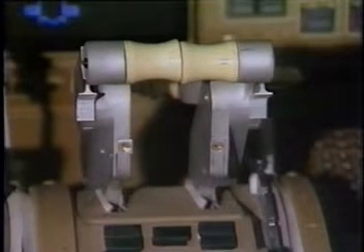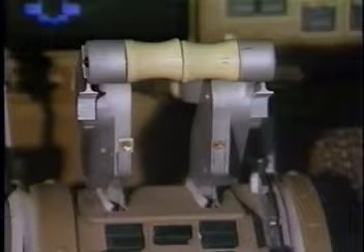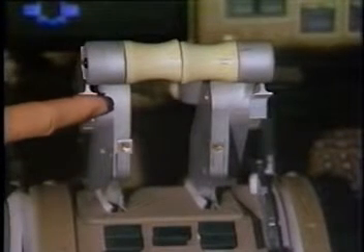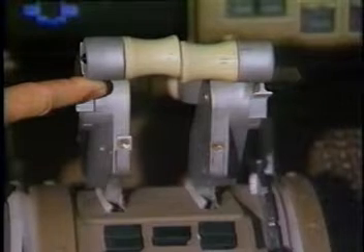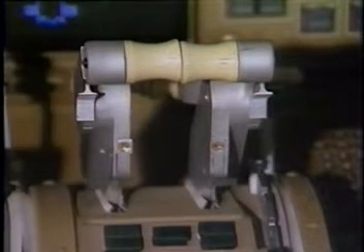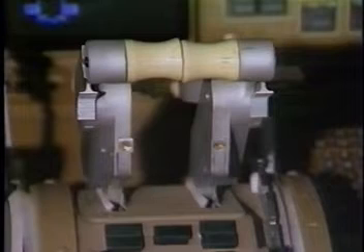The go-around mode is used for rotation and climb-out after an aborted approach. Pressing either of the go-around switches on the thrust levers initiates go-around for the AFDS and thrust management systems.